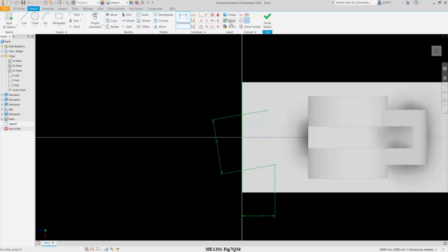Okay, so now I want to make sure that both of them are vertical. In this case, click on this point to this point, and symmetry, point about the middle line. Notice the 2 points are being changed to purple.